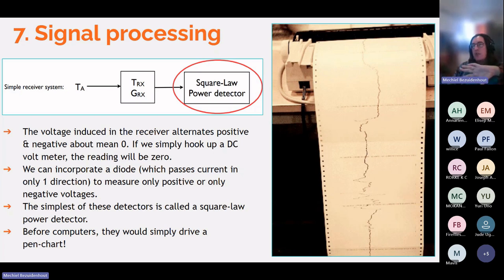Then when you do the signal processing, you can decompose that signal, you can channelize it. So you can divide the signal up into distinct frequency channels using a Fourier transform. And then each of those channels independently corresponds to the flux within a specific frequency range. Does that answer your question?